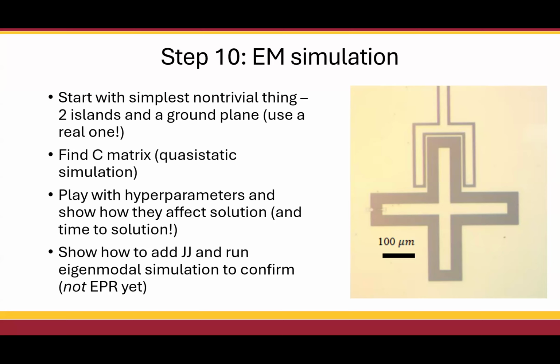Do not do EPR yet. Okay, EPR is fantastic. It really gets you everything you need. They will not understand it correctly, and they will not understand how to know when it's failing. EPR, the biggest danger is that it's so good at giving you everything that you're really tempted to just say, simulation, EPR analysis, done, without actually understanding any of the steps in between.